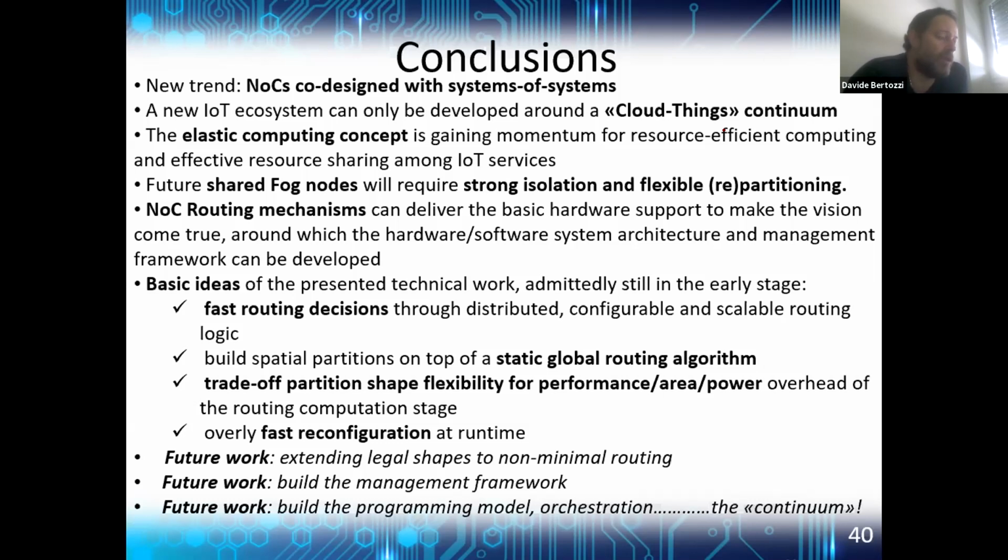And that's why I was telling you in the beginning that you need to co-design your system architecture with the synchronization scheme of your network, because if you are splitting the network on chip into the voltage and frequency domains of the processing cores, then your routing paths become extremely heterogeneous, and you have unpredictable congestion effects along the links depending on the relative speeds.